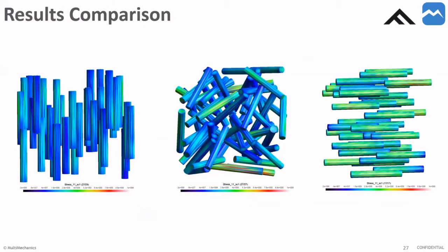The last step, you can see why a random fiber is going to be stronger and stiffer than transverse, but you can also see why the perfectly aligned is going to be superior to both of those by the way that they're aligned. So this is just kind of a general why we want to align fibers, and this is a big issue when even if you're doing injection molded, you're going to have areas that are going to have high alignment, and some areas are going to be completely random. So that's something to factor in when people are doing manufacturing with these types of materials.